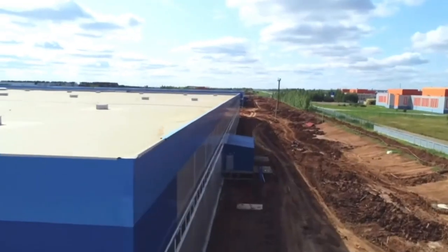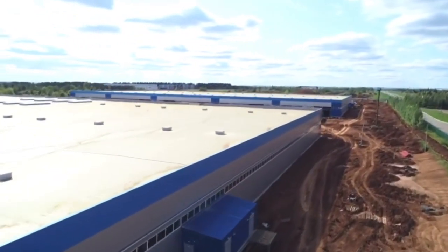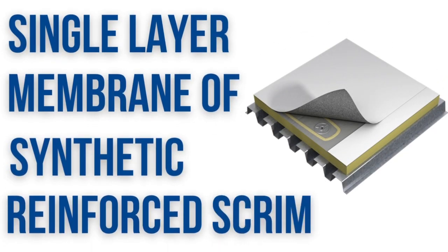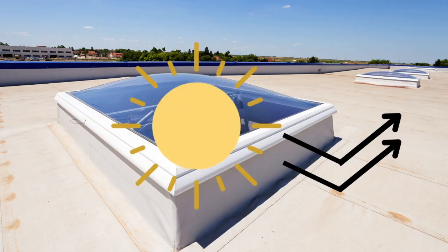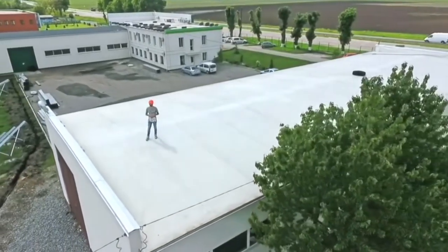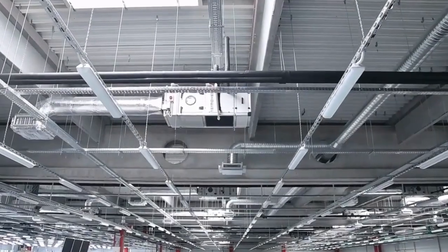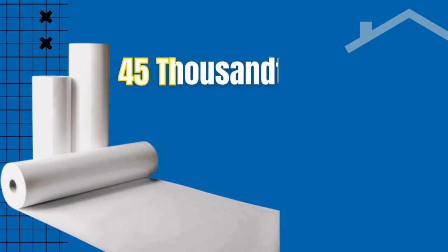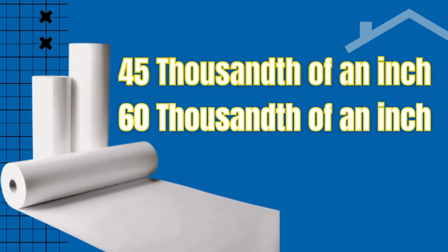TPO has been around for 20 years and is one of the youngest and fastest growing commercial roofing systems on the market. This material is made up of a single layer membrane of synthetic and reinforced scrim. Now, because this material is white, it does a really good job at reflecting the sun's UV rays. Because it has a protective system that deflects the sun, it helps reduce the demand for air conditioning in hot weather.